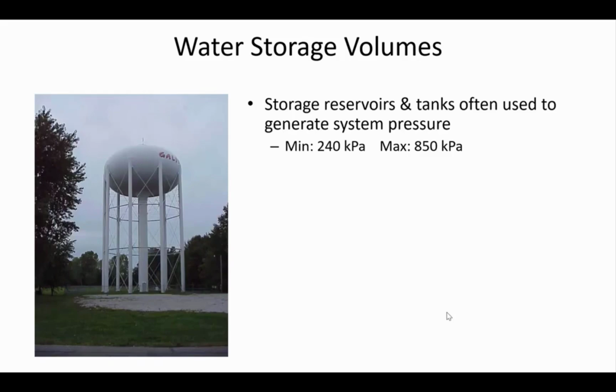We have a reservoir in the project because we want to, number one, pressurize the network. You can pressurize a drinking water distribution network with pumps, of course, and in a lot of flat places that's how they pressurize the water network, is just to have a pump operating at all times, and that adds pressure and the water can be withdrawn from people's faucets.